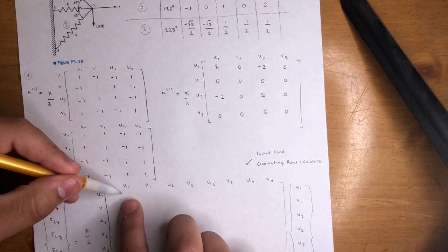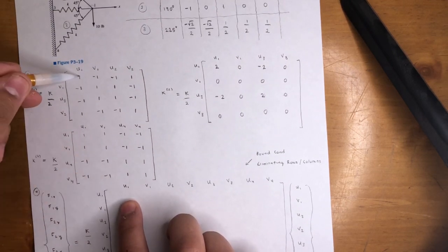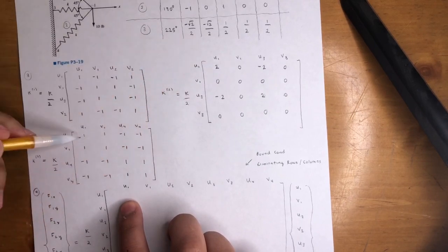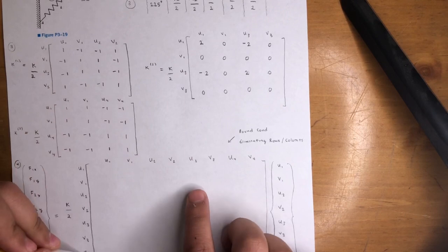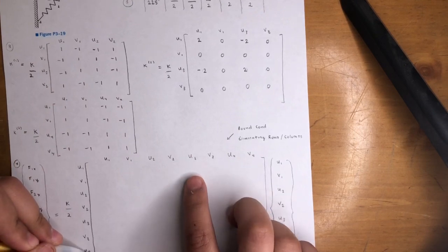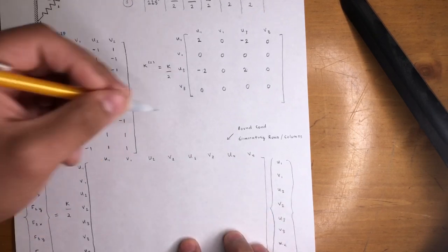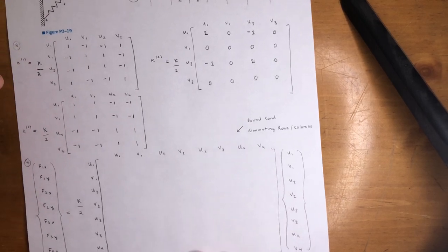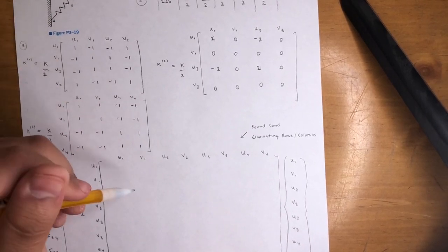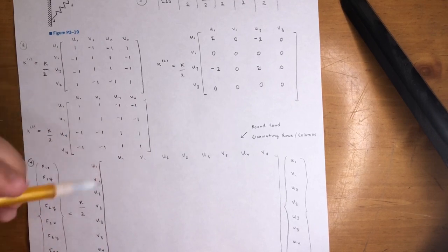So anything that's U1, you've got to add it. So it's 1 here, 2 here, 1 here. This is going to be a 4. You've got to do that for every single one. Find U4 and U3, for example, if there's any, and then work with it that way. It's going to be crazy if you do that. So start applying the boundary conditions before you assemble the matrix.